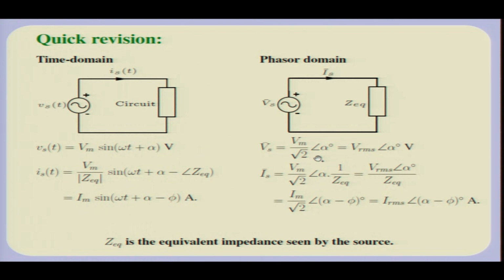For example, a 2 port network will have 4 terms, 2 driving point terms at the two terminals and also the off diagonal terms. So, you have got an impedance matrix connecting two voltages and two currents if you have got a two port network. But for this simple circuit, of course, you have got a single port network, and this is simply a summary of what we have done so far.